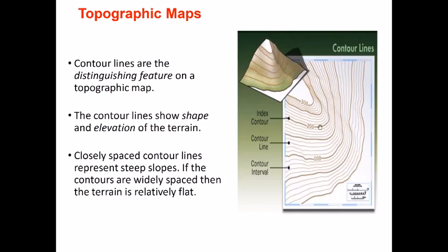And sometimes the lines can be very close to each other, and it's not possible for you to write down the elevation of every line. So in this case, if this is 300, this is 250, and this is 200, you can write 290, 280, 70, 60, 50, and so on, but it makes the whole map very crowded. And since the contour interval, that means the interval between which you are making your contours, which in this case is 10, remains the same, you don't have to write the elevation for every point.